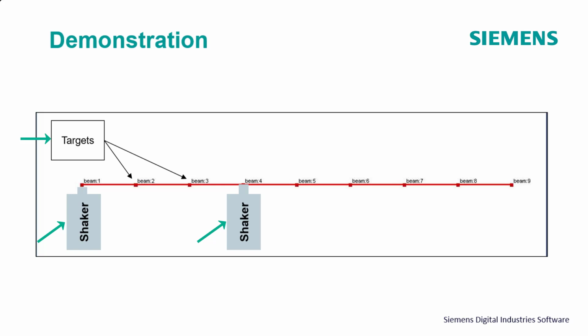So if you were to do that without principal component analysis, you over-predict the results. And then when we do principal component analysis on this beam data, we realize we don't have two sources. We really only have one because we fed the same signal to two shakers. And that's example one we use in the training class.